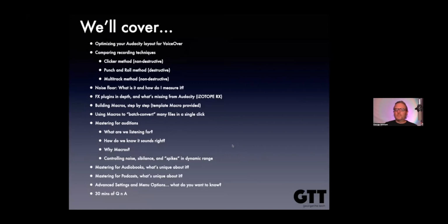Next, we'll go into how to use a macro to batch convert many files in a single click. So you don't have to just apply a macro to the project you're working on. You can apply it to a bunch of files. And that's a nice way to speed things up dramatically.